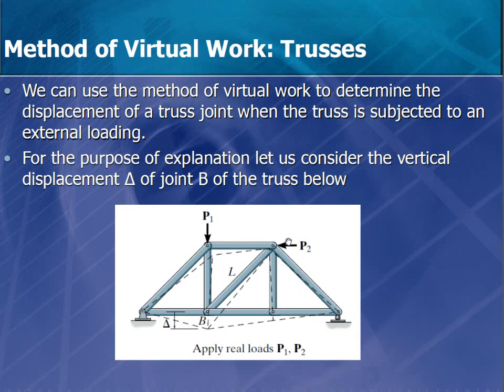When those two loads are applied to all the members, we know from statics that I can calculate the internal forces, yes? So what do those internal forces mean? Each of them has a deformation. When we calculate the force in this member, I can calculate the deformation inside it, yes? And for this one and the rest of them. So it means that each member will absorb some of the energy that comes from those loads, and according to its shape, it's going to deform.